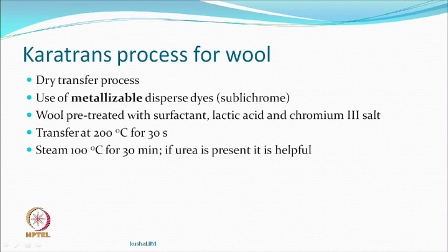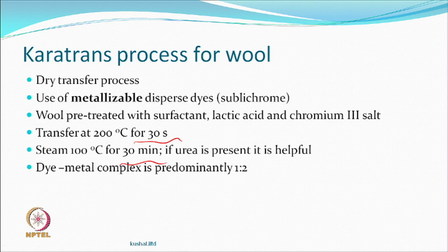So, there is a post-treatment which is a long period. You can appreciate it cannot be a process as fast as the dry transfer. After the transfer has taken place, you still have to steam. Look at the comparison: 30 seconds versus 30 minutes for fixation. Urea may also be available in the pre-treated material, and then you wash it off.